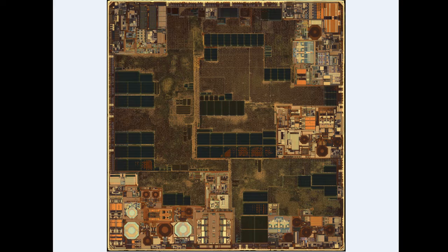So as you can see on this polysilicon layer, the different transceiver blocks are clearly separated from one another, with this being the Wi-Fi, and this being the Bluetooth, and this being the GPS, and probably the FM receivers here, and other analog circuits in here. With that in mind, I will focus on the Bluetooth block that we currently have in our labs and take a look at the Bluetooth clock generator.